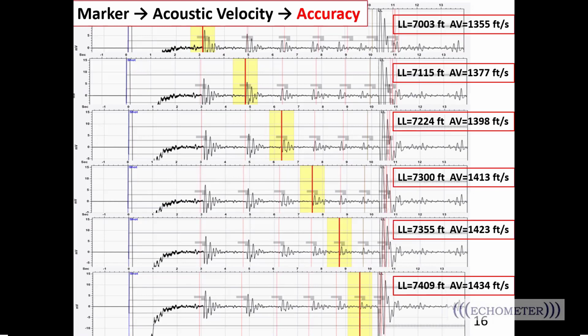If you use less differential pressure, the round trip travel time will be exactly the same. It won't make the composition of the gas change. It won't make the pressure of the gas or the temperature of the gas change. It's just going to make a smaller energy pressure wave. So the echo from the pressure wave will be smaller as differential pressure decreases, and that's all that happens.